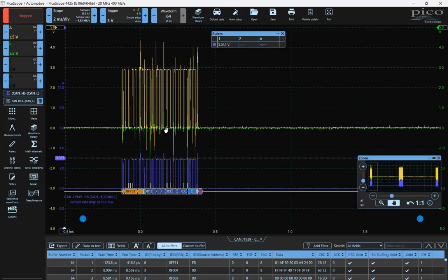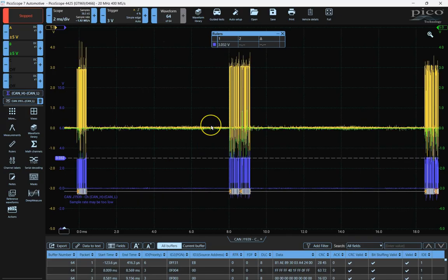So I've done this on real machines and showed technicians where I had a passively terminated CAN network, a large machine with 20 or more controllers on it, and short CAN low to ground, and no fault codes, no problem. Even though the pattern looks terrible like this, it still functions. It's definitely not recommended. It affects something called the signal to noise ratio. We're dependent only on CAN high, and you definitely wouldn't want to drive this machine on the road with CAN low shorted to ground.